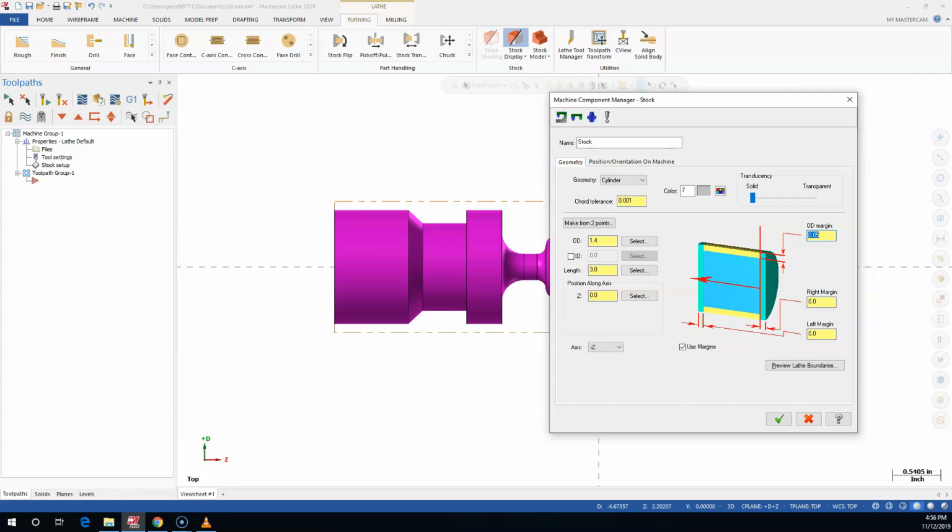The first time I checked this, same thing. I said, well, is this a radial or diametral? You know, is it adding on to the diameter or is it adding on to the radial? So I would set it and then see how much bigger it got, and it was quite a bit bigger. So we're actually adding that radially. So 50 thousandths is enough.